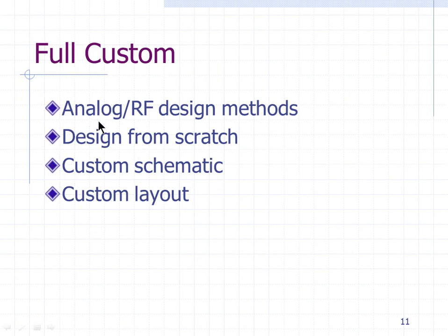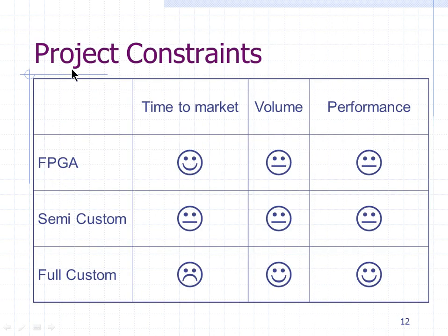Typically done for analog based designs. Analog designs are mostly done at CMOS transistor level design. Even for CMOS transistor level design, there is a language called SPICE. Maybe you guys have used it in one of your grad school projects or tasks somewhere. Right? So SPICE is another language which is used for analog design, where you create a structure of gates and transistors to create a bigger design out of it. Memories are typically done at analog level using CMOS transistors. So that is full custom ASIC design.